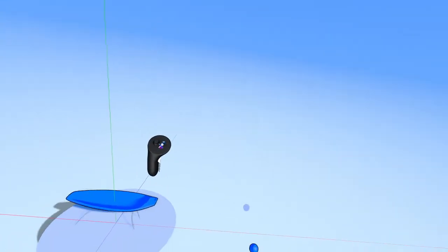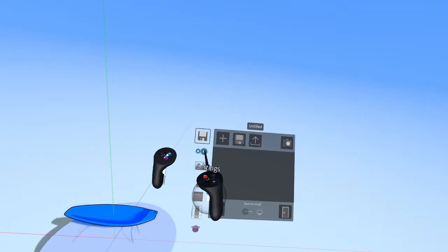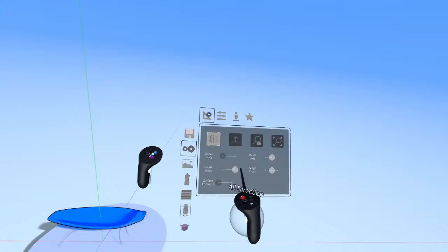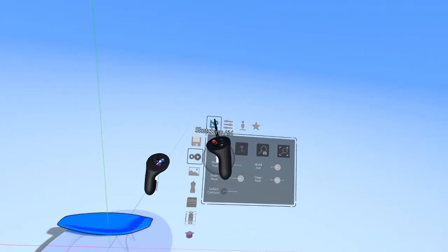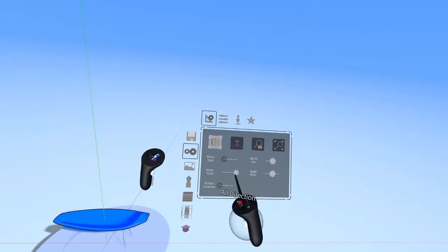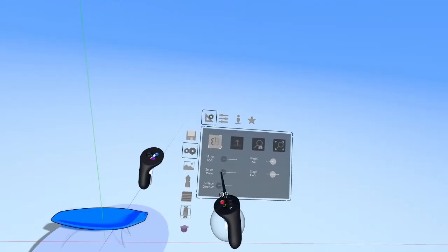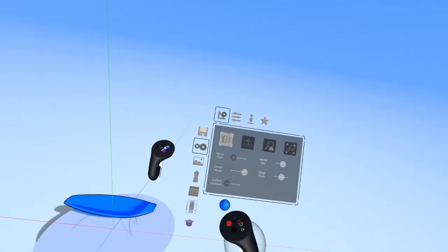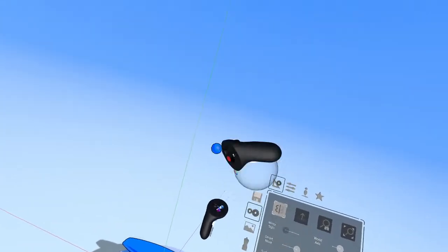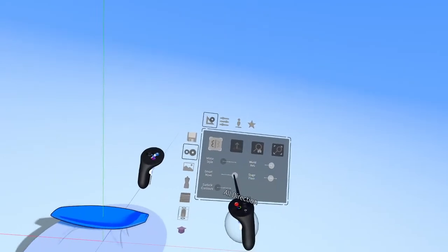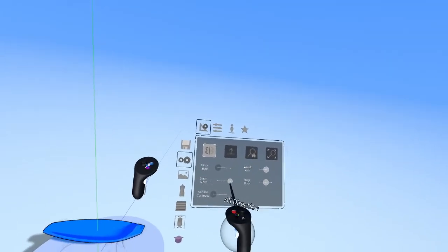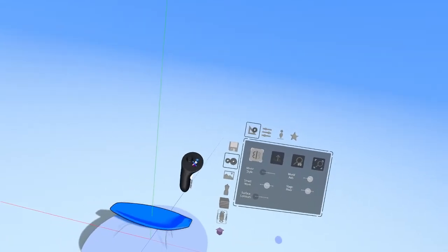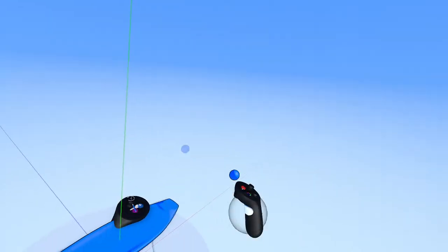And then if it's still not working for you, you should probably do this first actually. Go to the blue menu button, click Settings, and make sure you have Smart Move enabled here under Sketching Aid. Settings, Sketching Aid, Smart Move. You have three options: off, X, Y, and Z, and all directions. All directions gets kind of confusing because it allows you to move precisely in any direction. It definitely can be useful, but at first I would suggest turning it on to X, Y, and Z, because those are the axes that you can actually see and interact with.